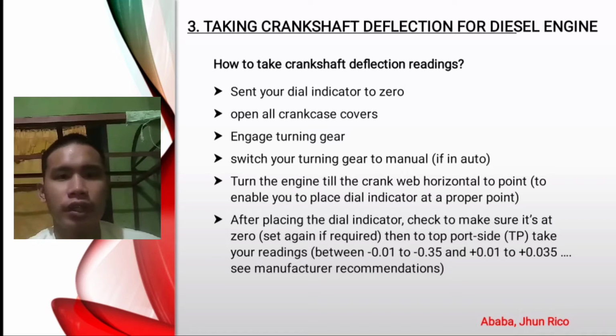So what are the precautions or the steps to accomplish the proper reading in taking the crankshaft deflection? First is set your dial indicator to 0. Second is open all crankcase covers. Third is engage turning gear. Fourth is switch your turning gear to manual if it is set to auto.